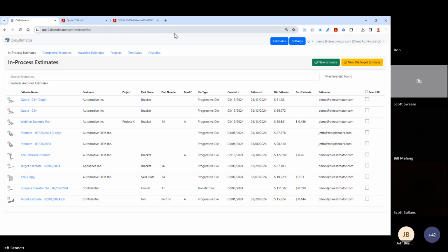Okay. And then second, on that same topic, are you able to bring in a DWG and click on the DWG for dimensions? You can, but you do that through the cut and paste method. If I have any type of file, I can capture the image from the screen and paste it directly into the application. And it actually works better that way than it does manipulating the CAD file. Okay, so you're bringing in a raster image, not a vector image. On 2D, we are, yes. Now we do bring in PDF, but not DXF or DWG.